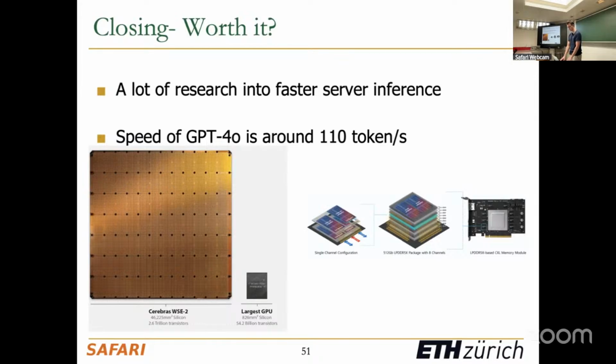I think this is an interesting paper because there have been other works that propose in-storage processing to accelerate LLM inference. So this does something fundamentally different. It goes aggressively, first of all, into the storage system because it introduces a lot of modifications: shorter bit lines, multiple planes, more planes actually. It introduces new logic inside to perform the FP dot product, and it also adds additional logic for the ECC. And it also does something different in another way.